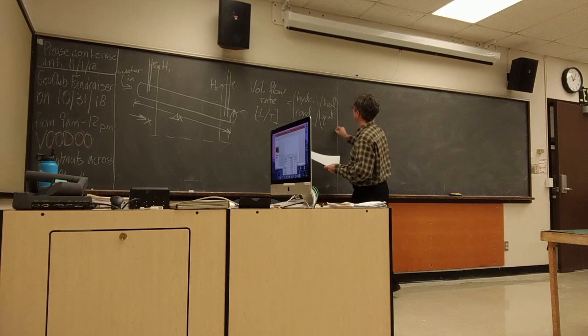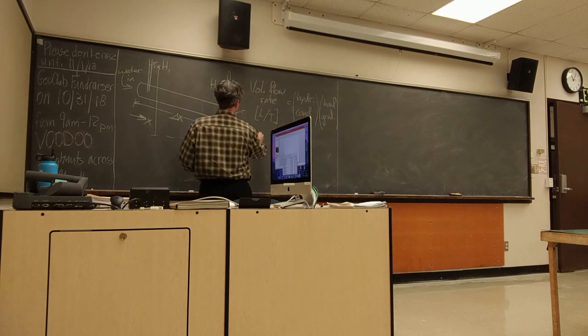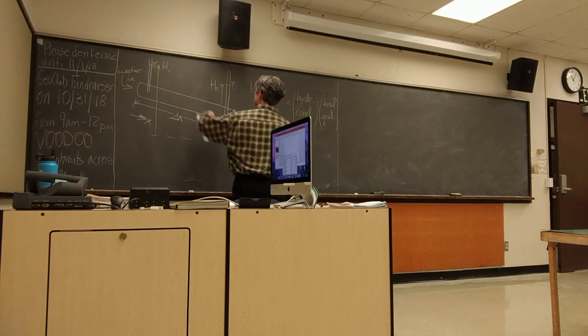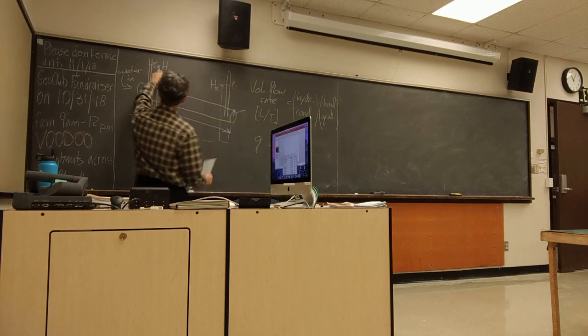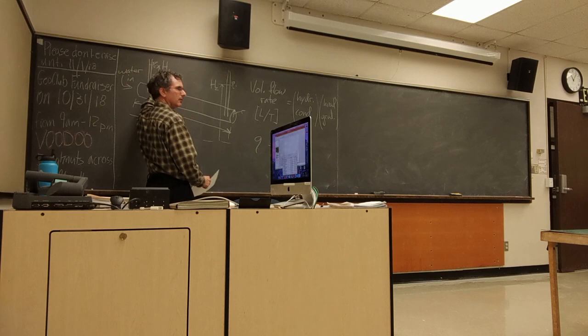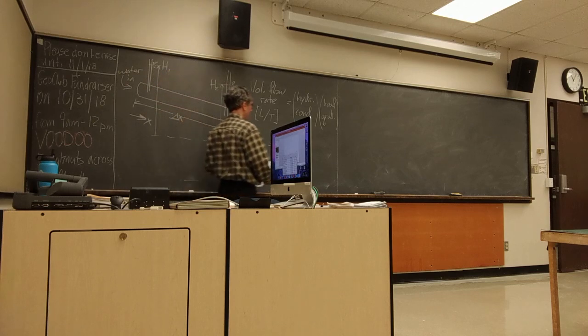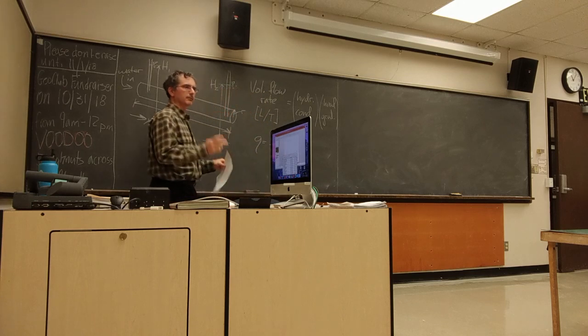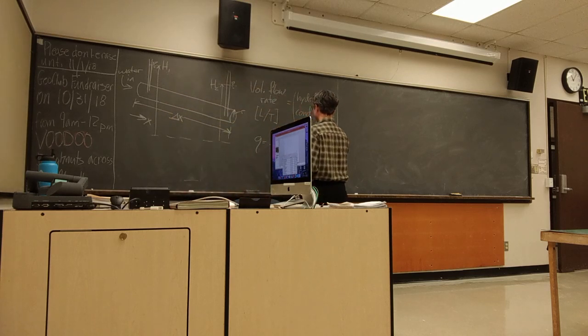Okay, so we'll give this a little Q, K-sat. The head at 2, H2, minus the head at H1. That reminds me I'm going to need a negative sign. Sometimes I sort of blow that off, but let's just be clear. So H2 minus H1 over delta x.